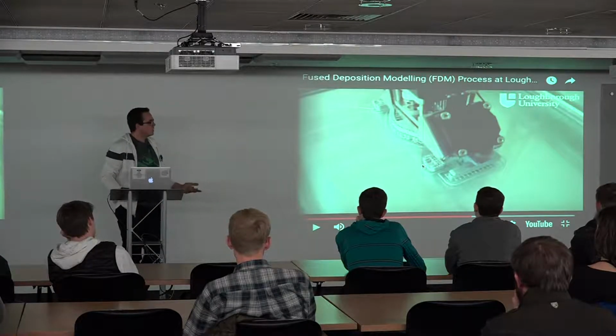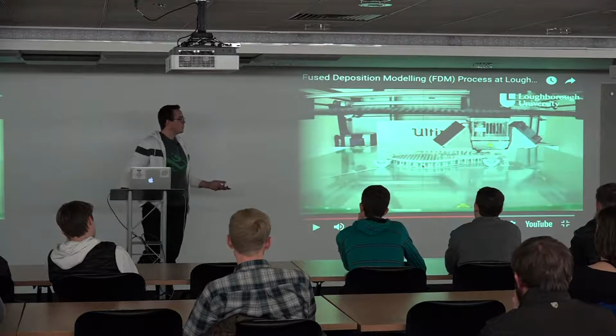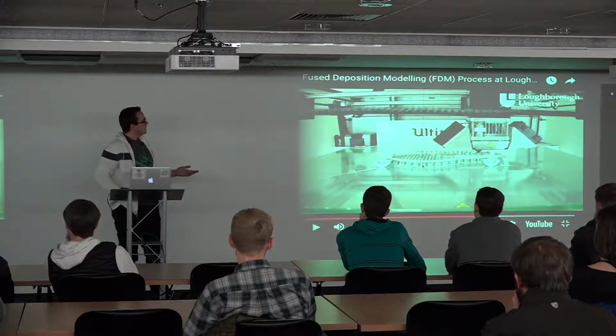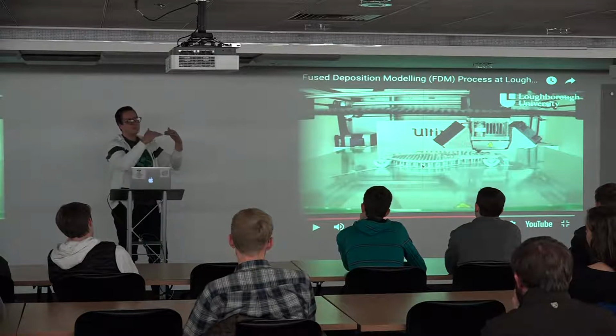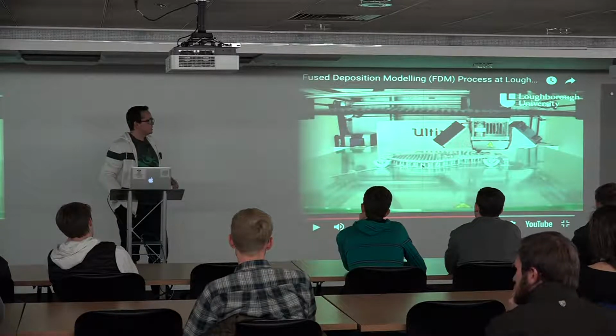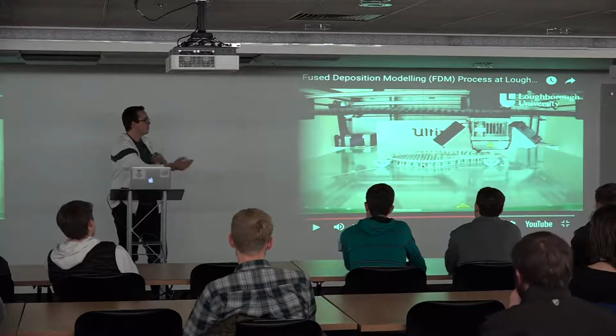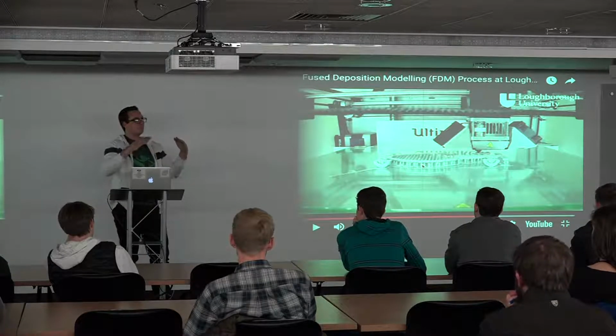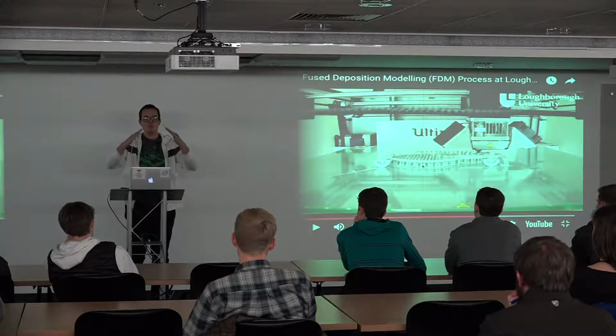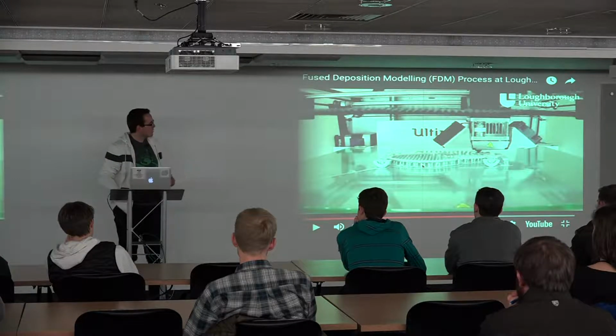But that's something to consider if you're designing your part with 3D printing in mind, then you can minimize those overhangs so that printing is easier. A lot of people will have more, like a 45-degree angle is pretty easy to build up. So if you can build your bridge with a 45-degree kind of tower that leads up to it, that's a lot easier to print.